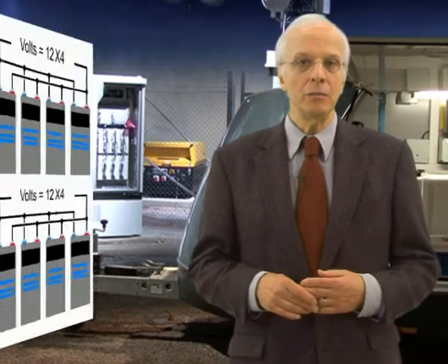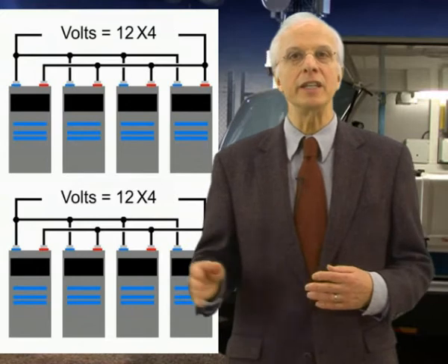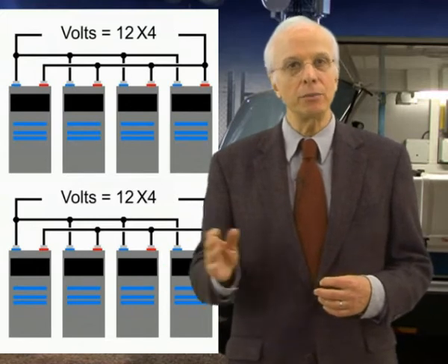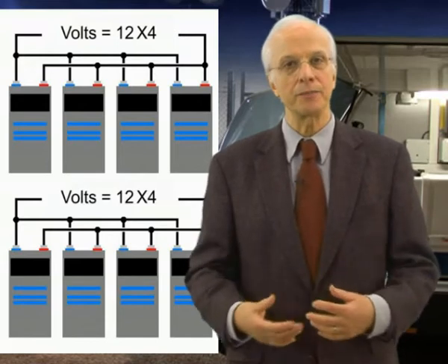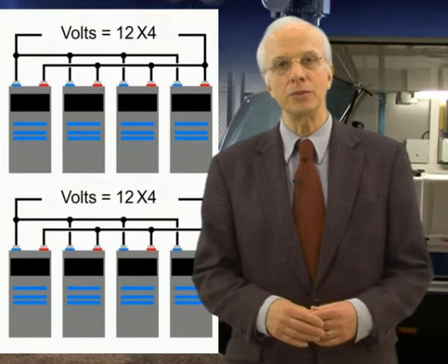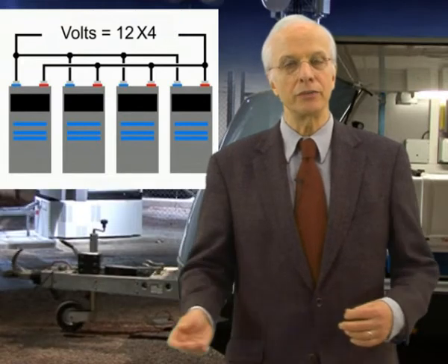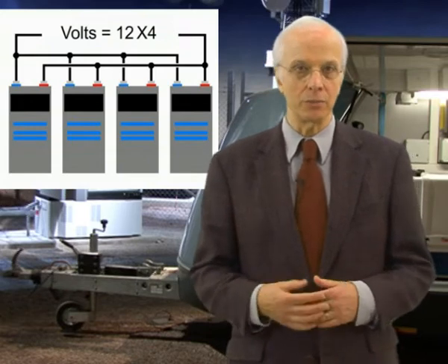To protect the telecom equipment against interruption of power supply, most battery plants are designed with 2 or more batteries in parallel. By connecting several batteries in parallel, reliability can be increased substantially. Now, during maintenance, you would then be able to disconnect one battery string from the power plant and still have 1 or more batteries in operation.